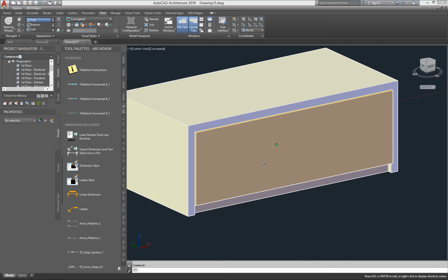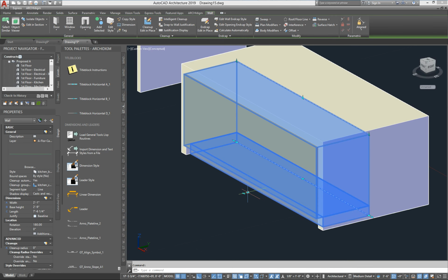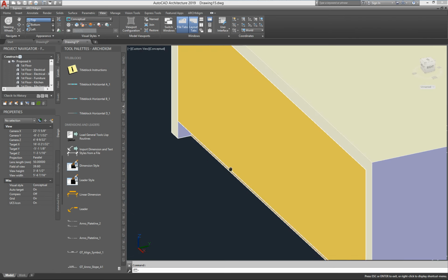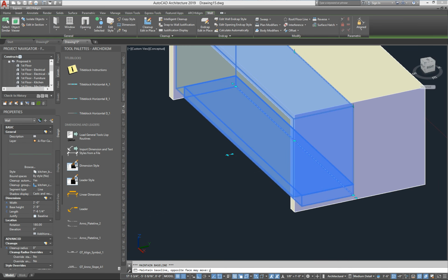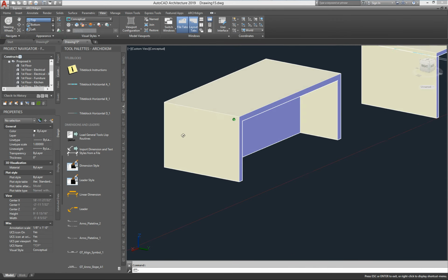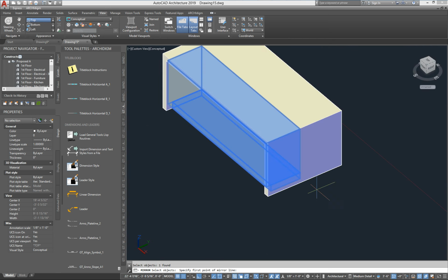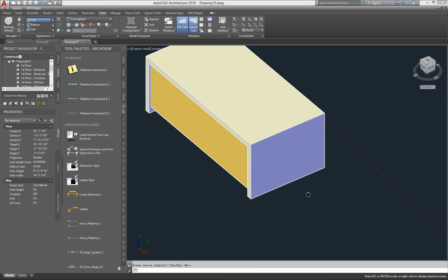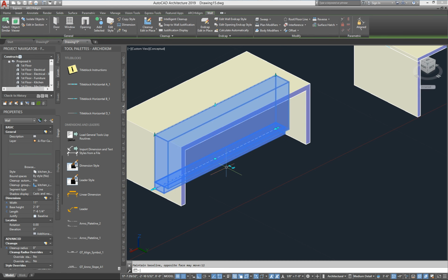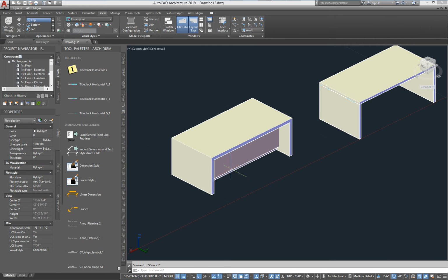Yeah. And so now I'll just pull it back. So I'm going to reduce the depth. I think it was something like that, 1 inch. Yeah. So now that lines up. Now, if you want to recess it more, you could do another inch, so you have a little bit of a reveal. And then on the other side, if you want cabinetry on the other side, we'll just do a mirror, and we'll mirror this over. Mirror, and then do midpoint. All right, and then that looks pretty good, but let's pull it in about 12 inches or so. Oh, that's very shallow, but you get the idea.